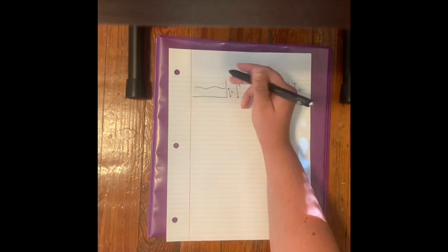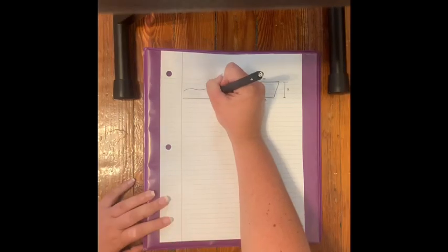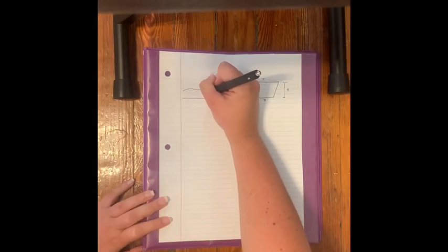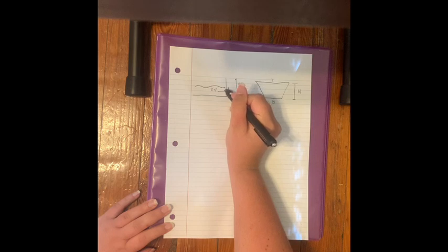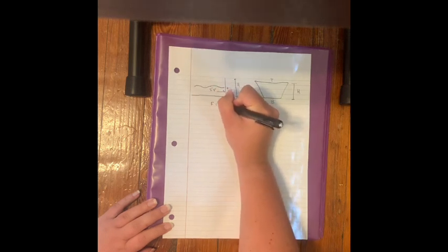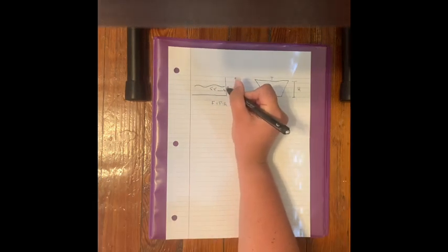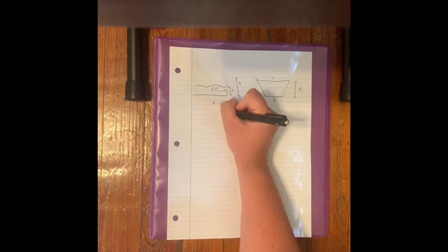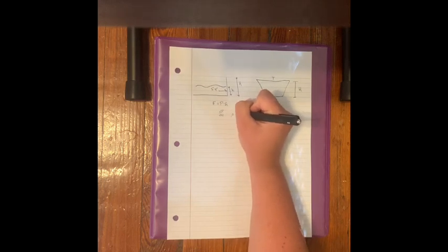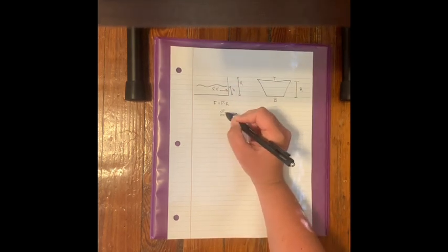So because our liquid exerts a pressure on our wall over this cross-sectional area, there will be a force due to pressure. So we know pressure applied at some cross-sectional area will result in this force, and so force is equal to pressure times area. We also know that pressure changes with height. So we're going to start with dP dz is equal to negative rho times acceleration due to gravity to find what our pressure is. To get to this equation, it was explained in a previous video.